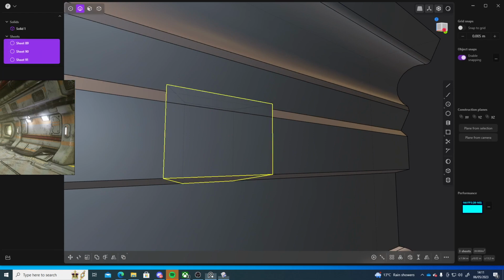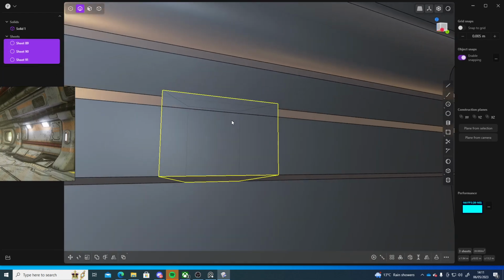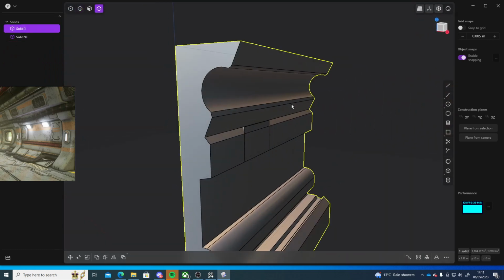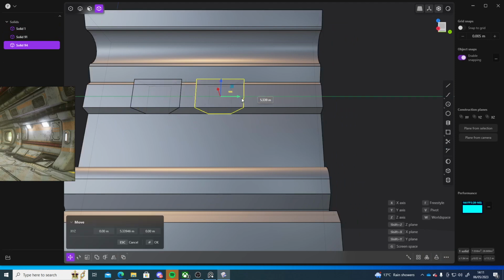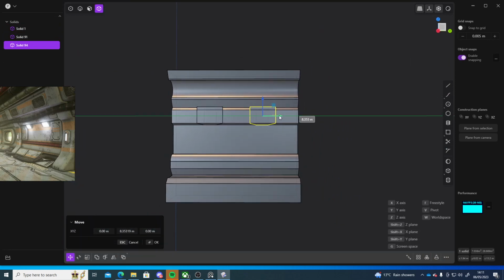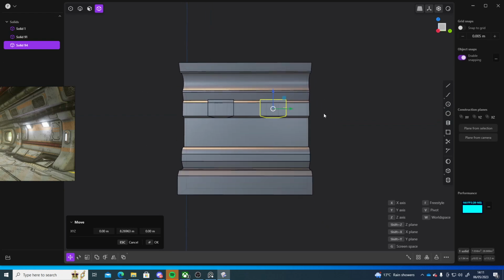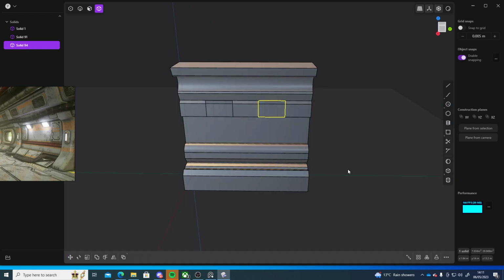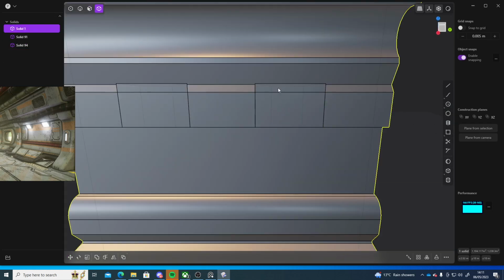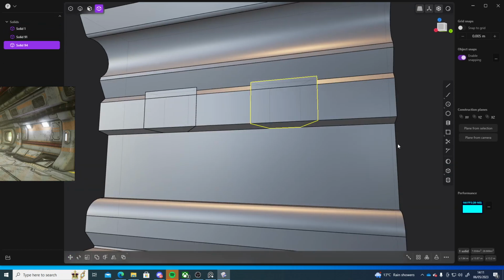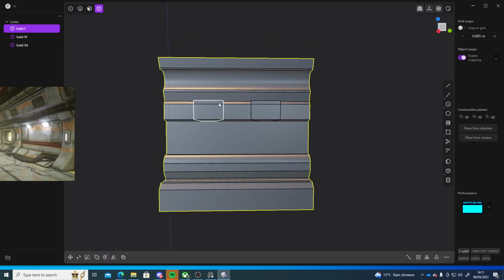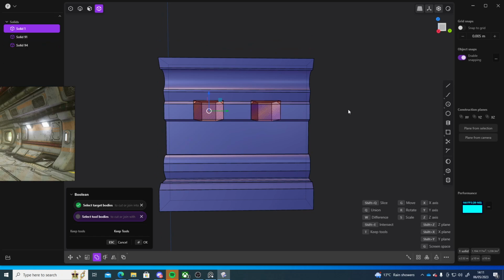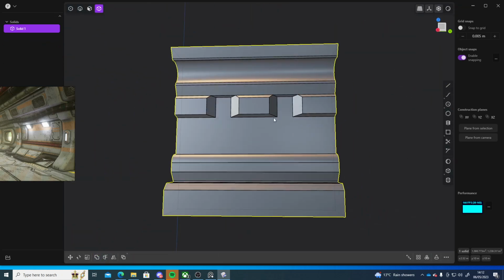Bring that back. Select all these sheets and press J, which should turn it into a solid, which it did. Then I can select this, press Q, right click. So it cuts that out, right? But I want to just duplicate this part here, move it over. Again, maybe I should have had this centered so that I could get it exactly perfect. But again, this is just practice. It doesn't need to be perfect, I guess. So select this, I'm gonna press Q to go into Boolean mode, click these two, then right click. And we get this quite interesting shape.